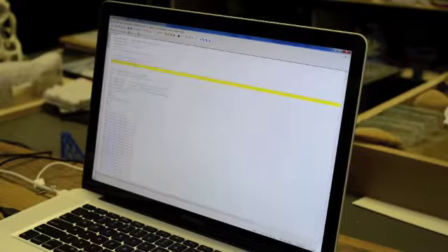And then here's our preview. So the information over here, this is telling us the tools we need. That's really helpful when we're downstairs in case we forgot, like if we set this up a few days ago and then we go down. So we've got 239 and 252, and then this is the shift that we just did. So X was 120, Y was 60, Z was 0, and spindle speed for the first part of the code is only 9,000, which is fine. That's what we had set up.